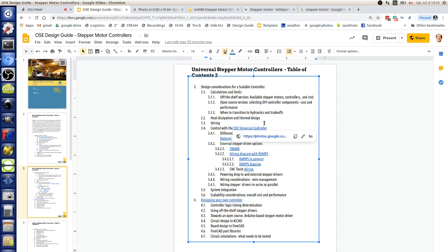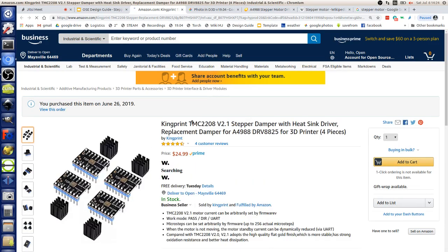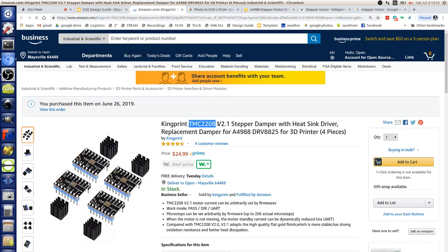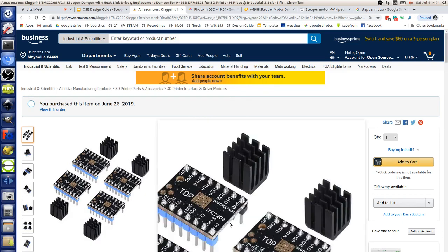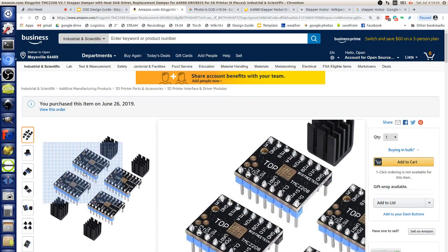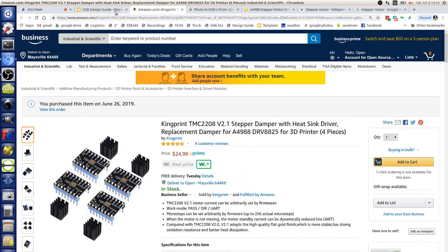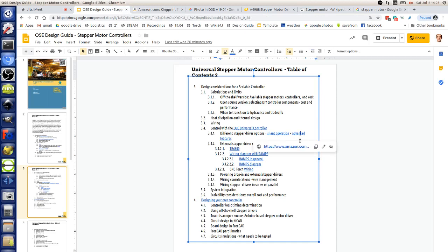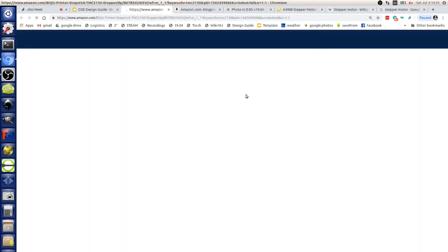So let's start with options that you already have that fit in that form factor. Right now, off the shelf, you can also get these other Pololu-like stepper drivers. These are the TMC2208, same form factor, but their advantage is they actually provide silent operation, so you do not hear the stepper motors humming and making music. It's pretty silent.